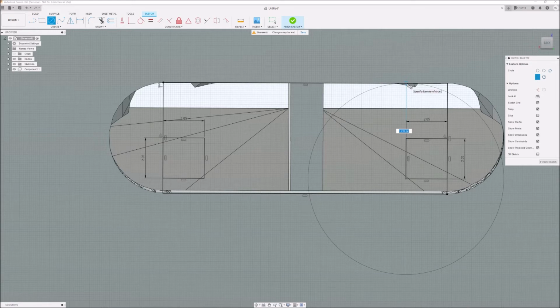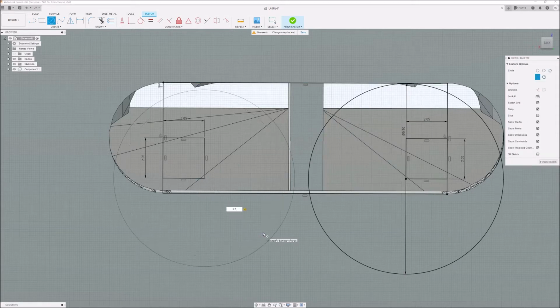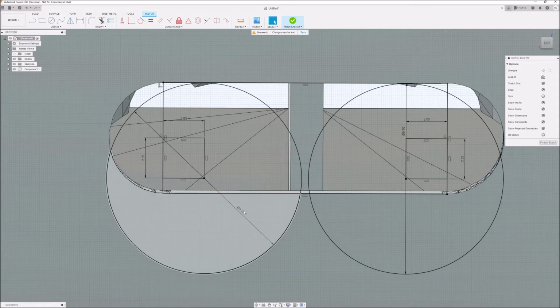9.739. So let's just go ahead and type it in manually, 9.7, and then hit C for circle and go off of this point, 9.7, hit enter, and we should look pretty good. If I were to go from the edge of the circle here, oh, I forget how to get to the exact, let's just do it this way. I'll hit L for line. I'm gonna go up here to 180.